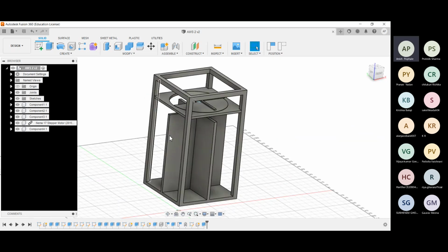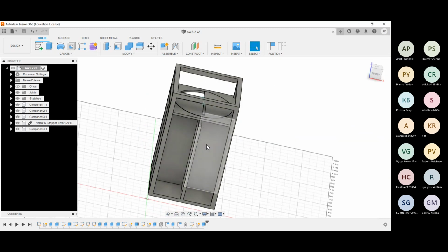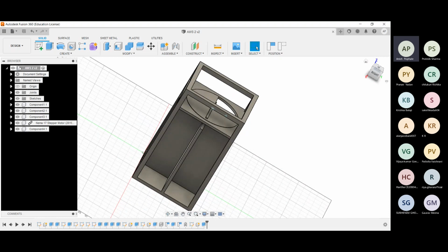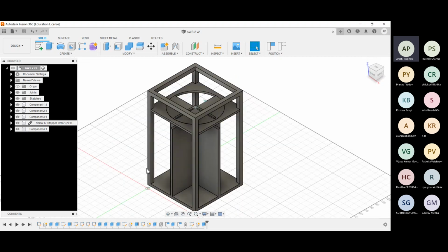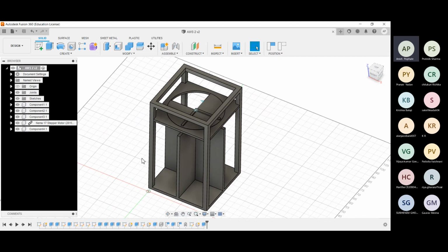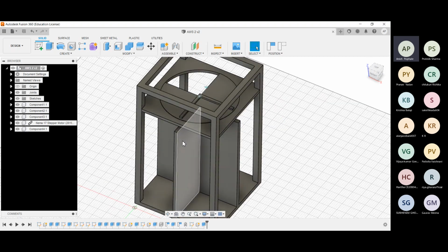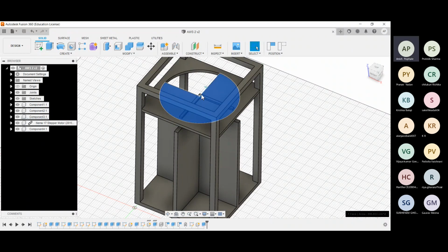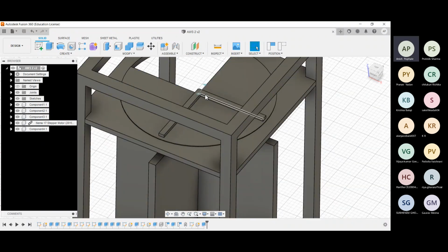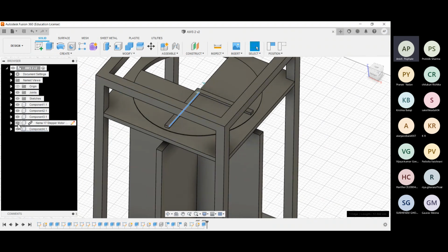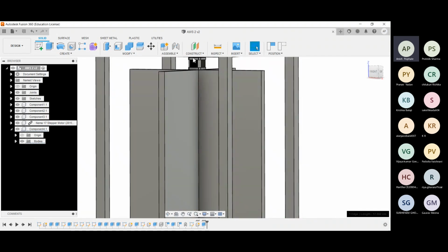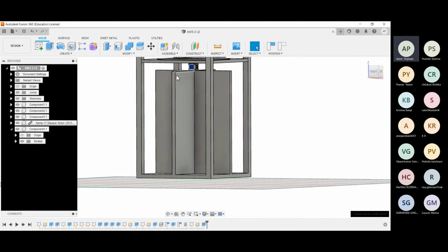As you can see, there are four compartments in the waste segregator, one for each waste category. Then you have this 3/4 disc, and you have this brush which will sweep the waste into each of the compartments. And we also have one motor here which will control the 3/4 disc.